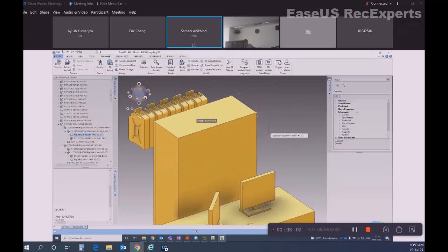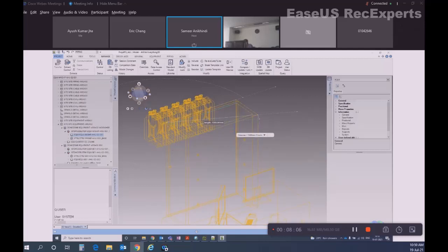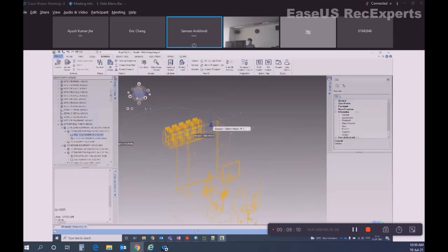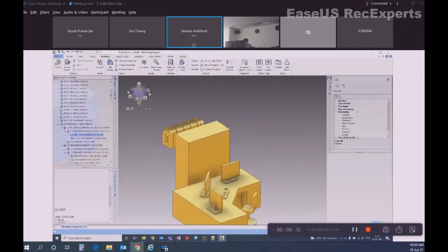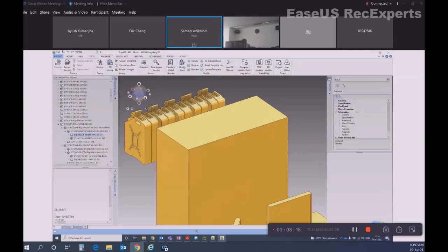Right. And it also gave me the angle. What is the angle in that plane? So there is a snap called dynamic hints, or F12. If I don't use this dynamic hints, the northing and easting will not be visible. Only the shortest distance will be visible.